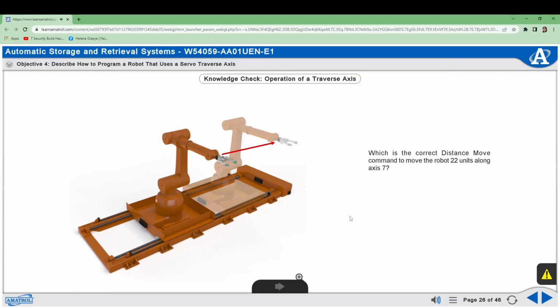Describe the operation of a robot program that uses discrete I/O handshaking. Like other control devices, robots can handshake with other machines. Robots interface to other intelligent controllers to coordinate production operations. To communicate to other devices, robots often use discrete I/O handshaking. A common application of a robot using discrete I/O handshaking is in a multi-station production system like the one shown.